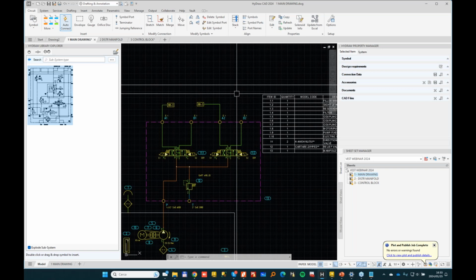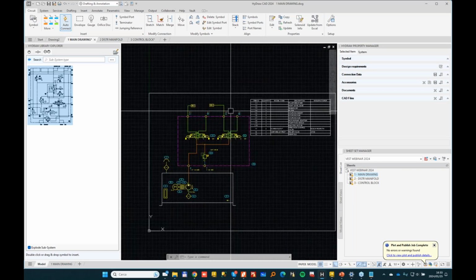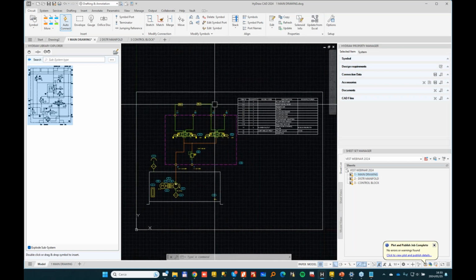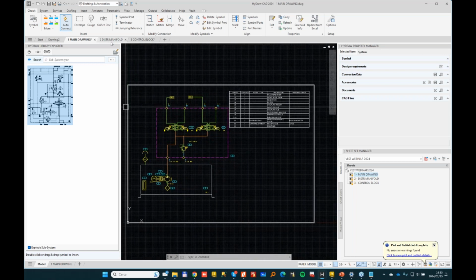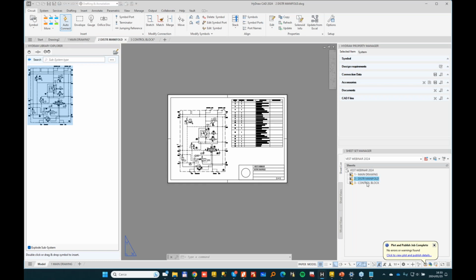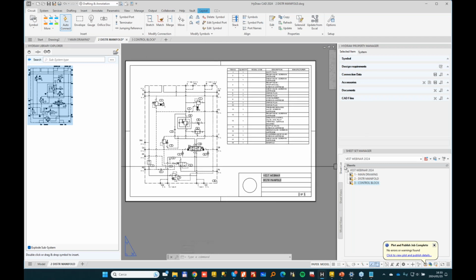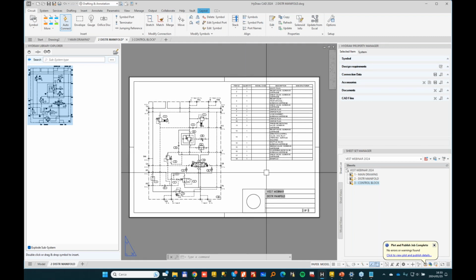this technique. The biggest benefit I can see in using sheetset is that all the operations are faster, lighter, because the files normally are smaller. There are not too many components in the same drawing, and you can switch between documents really quickly. You don't waste too much time with plotting, because basically if you do good template, then all the pages are preset for plotting, very well configured.